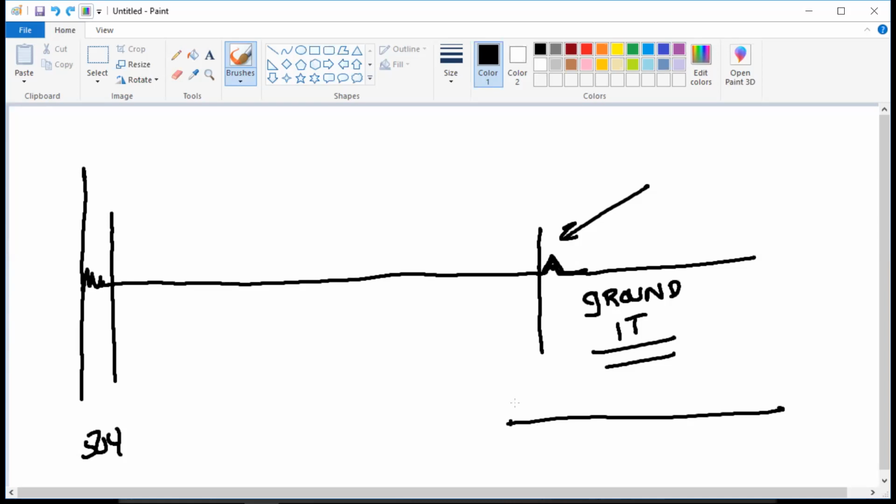All right, you send them down there. Hey, man, put your ground on. Nothing happens. What's wrong in the dirt? You have a what? Open cable. You've got an open cable. Okay, those are very difficult to find.